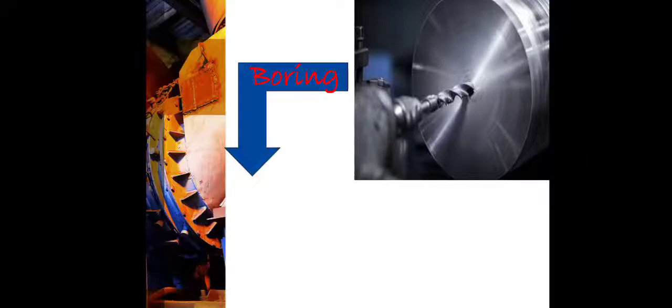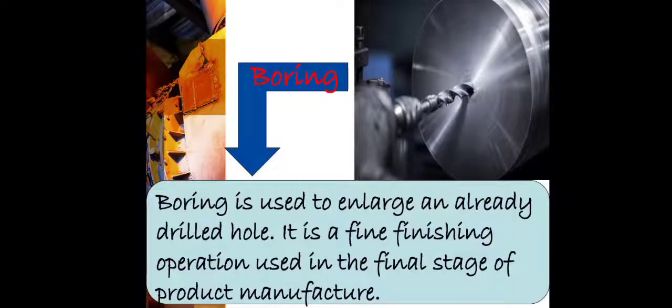Another one is boring. Boring is used to enlarge an already drilled hole. It is a fine finishing operation used in the final stage of product manufacture. When we talk about boring, it is applied after drilling. When the metal has been drilled already, you can now apply boring, because boring is just used to enlarge an already drilled hole. It is like refining the hole, applied in the final stage of product manufacture.